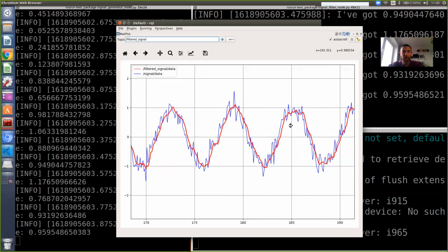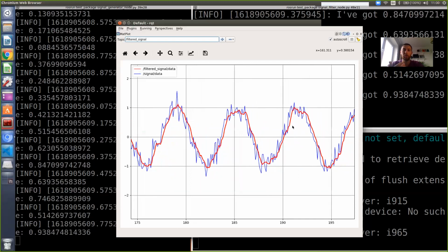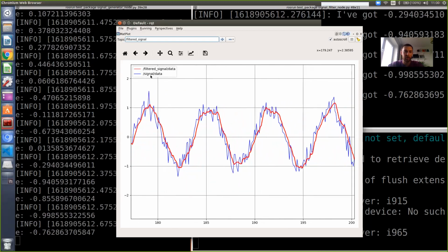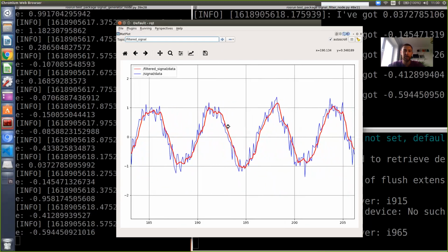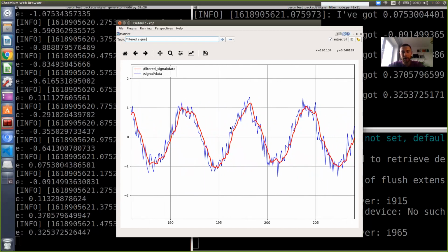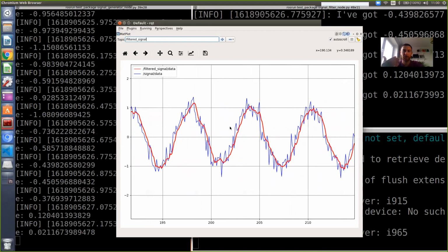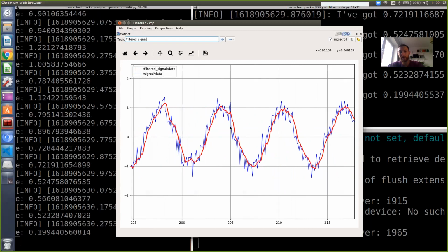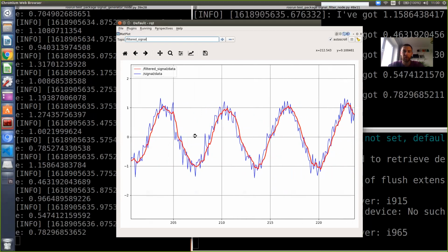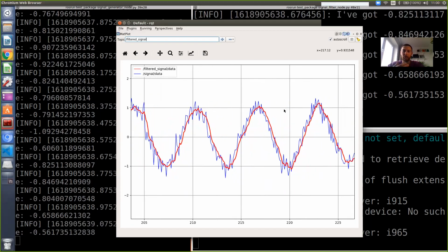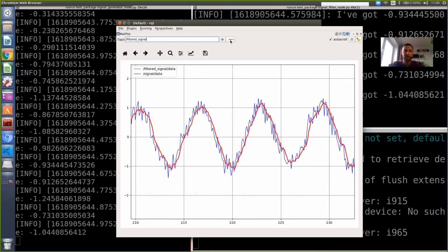So we will continue working with the same code on the next lecture. We will modify it. We will first introduce our own message type, and we will substitute this simple float32 message we used today with some specific, custom message type we would program next time. Also, we will discover new types of communication, which are services and actions. And we will work with the parameter server, as I said, to control this window length we use to filter our data, not compiling or modifying source code every time, but just changing the parameter value on the ROS parameter server.